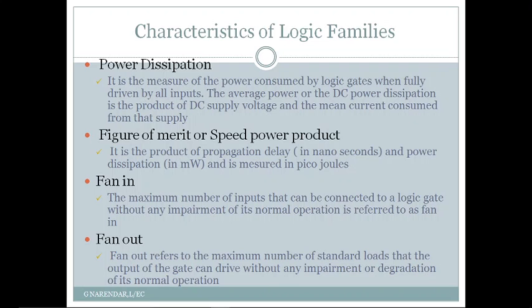That means we cannot connect any number of inputs to a logic gate. There is a certain limit on the number of inputs that can be connected, and this depends on the current requirements. So depending on the logic family, the maximum number of inputs that can be connected without degrading the performance of the logic gate is specified by the characteristic called fan-in.